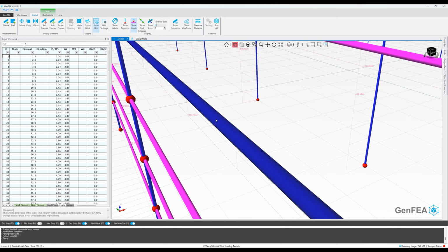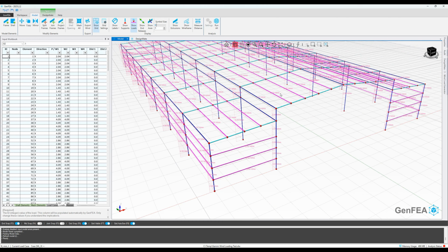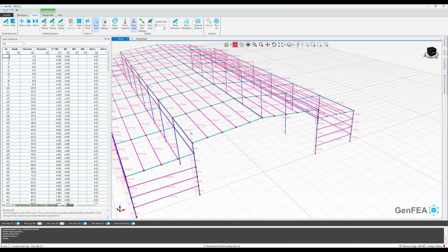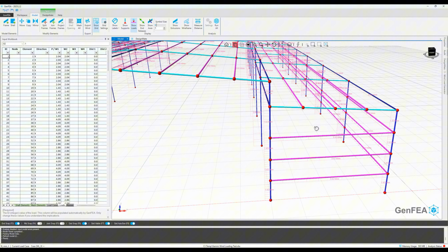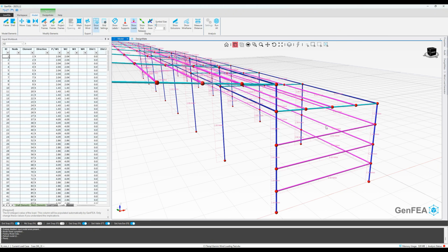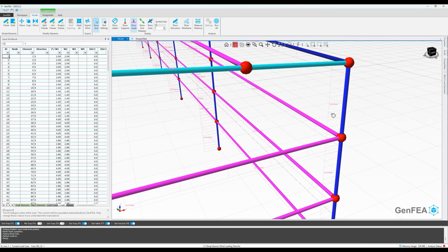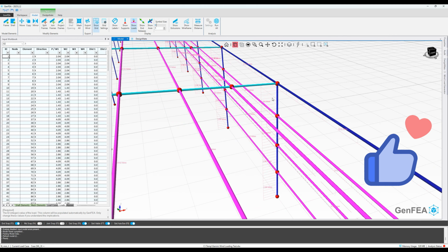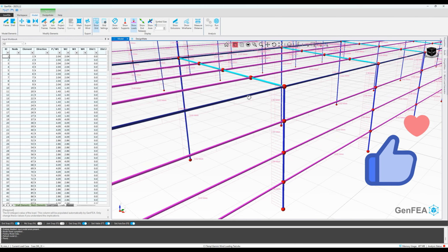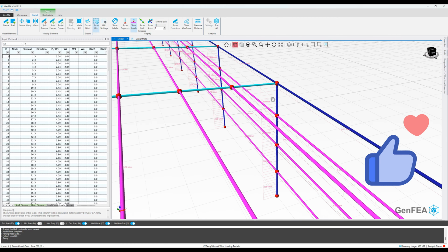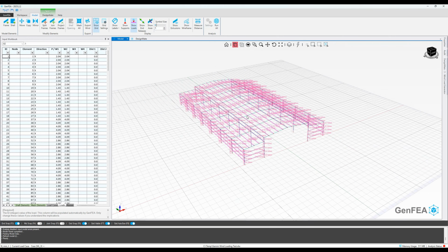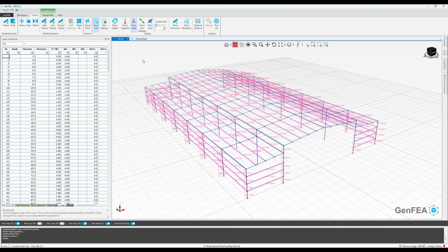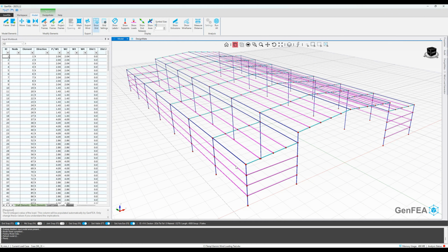Again, I probably should have split my roof purlins and side rails into different design groups, and instead of saying apply uplift on all the purlins, I should have been clear and said roof purlins only. But it's applied them correctly. Nothing here is out of place. All the loads apply to the elements that we've asked for, and all the reasoning is present in the output from the LLM. This is absolutely fantastic. It's generated in excess of 300 loads in the model, and calculated those correctly based on the prompting that we've provided, in a minute flat.